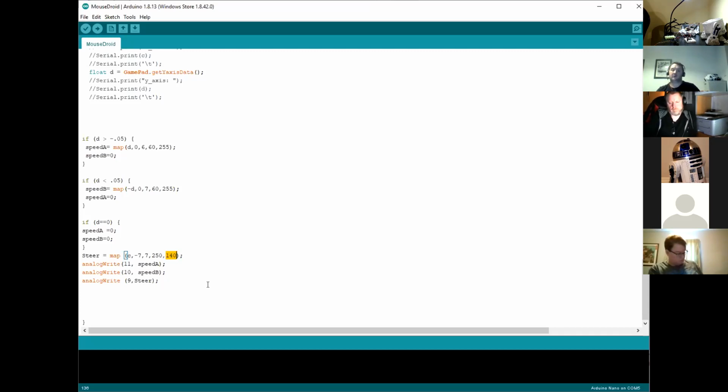And what you can do with a continuous servo is you have to play around a little bit to find where your dead center is, whereas the servo library does just kick out the 1,500 microseconds, which is what it requires to stop a continuous servo. But this is the reason that this has not got those definitive numbers, because I'm not using any library. I'm just writing straight out to it, which isn't the best thing in the world, but it works.